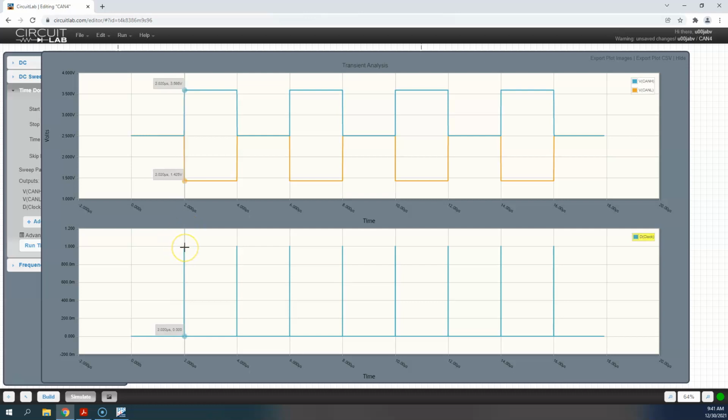So here's our clock down here. You can just imagine each one of these. This is 2 microseconds, 2 millionths of a second for each bit at 500K. At 500K, we're going to expect this every 2 microseconds. We're going to read, is this a high or is this a low? Is it a logic 1 or is it a logic 0? And then that would be interpreted.